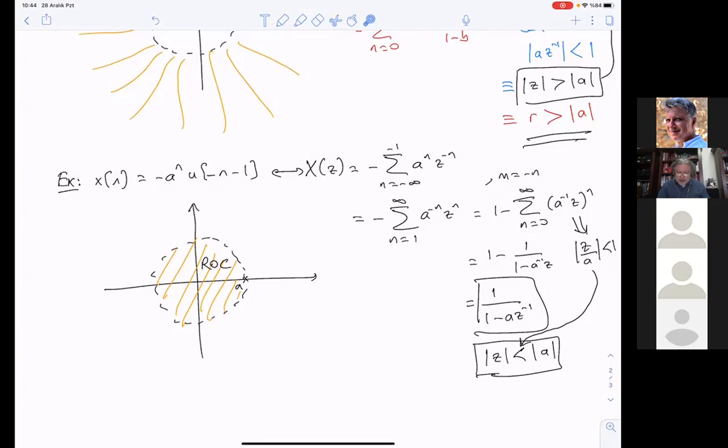And just like the Laplace transform case, the inverse Z transform is a difficult concept, and we usually invert by trying to write the expression in terms of a Z polynomial. If you can convert everything into a Z polynomial, then it means that you found the signal, because the signal values are the polynomial coefficients. But for instance, this one is not a Z polynomial. It is 1 over a Z polynomial, which is not a Z polynomial, but it can be converted.